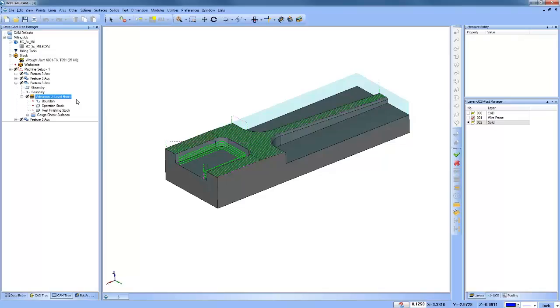okay? So really what you've got to do is have your toolpath set up as far as your tool and your depth and width and everything else, and now you're just looking at editing, whether it's extension or some of the feed rates and things like that. So you get the toolpath done first, and then you go in and use the editor, and you can layer edits on top of it. Does that make sense?